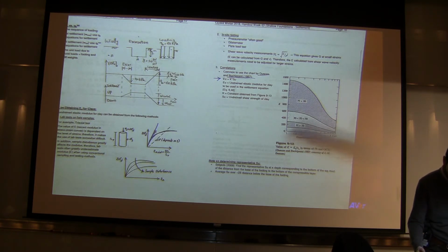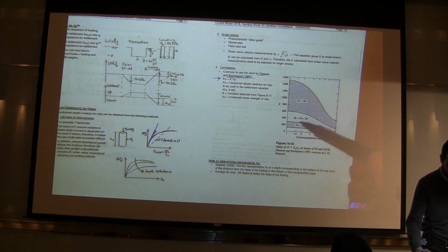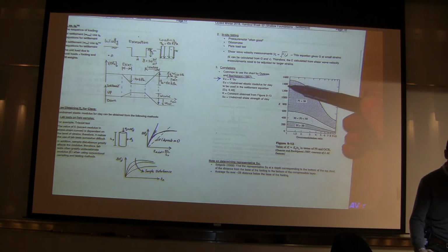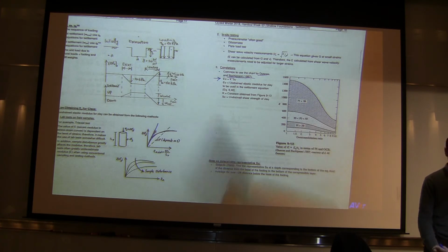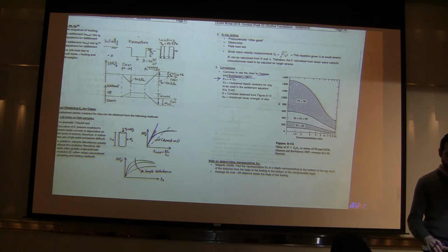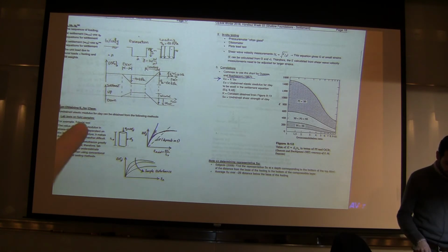So going back here, you have OCR here, and then these are different ranges of PI. What is PI? I'm sure you know it already, but plasticity index is LL minus PL. So PI less than 30 is this range. PI between 30 and 50 is this range. PI more than 50 is here. And this K value, depending on what PI you have, could go up to 1400. Then you pick that K value, you multiply it by undrained shear strength, and that gives you the undrained elastic modulus that you need. Very practical equation and graph, very commonly used in practice. Any questions?